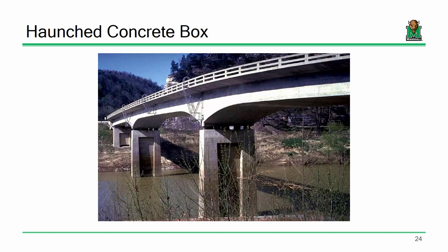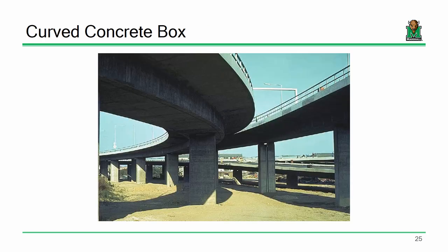We can still do things like a haunch girder, increasing the depth of that girder where we're going to need it, where we're going to need those maximum forces and what have you. We can also do similar things with concrete as well. We can curve it, use that similar box shape, get that torsional behavior that we like.